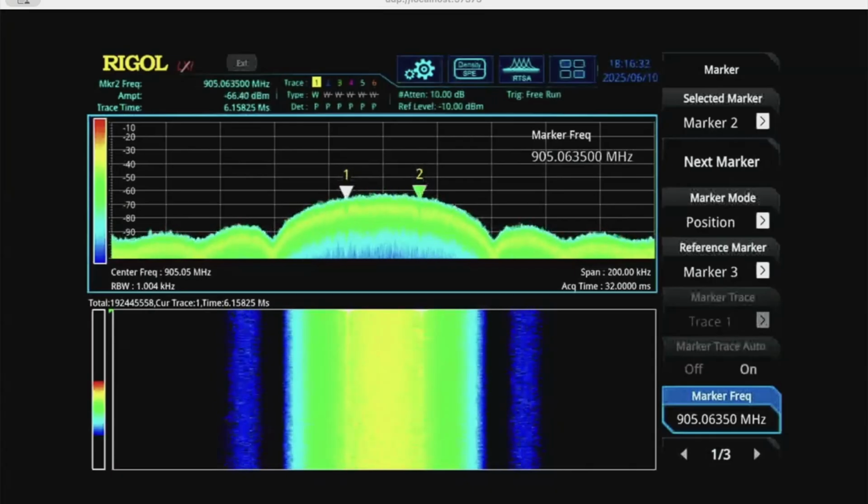You're dealing with a signal that's designed to have a constant envelope, and almost all the energy is in that main lobe. And so that's one of the several reasons why we selected minimum shift keying as the modulation that we wanted to transition to, that we wanted to evolve to. The initial design was 4-ary FSK, and if you look at that spectrum, you'll see that it doesn't quite have the same picture.